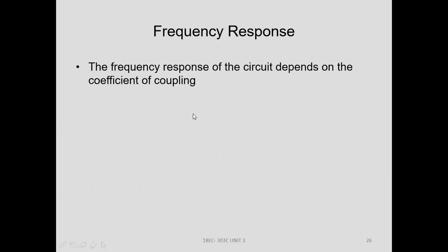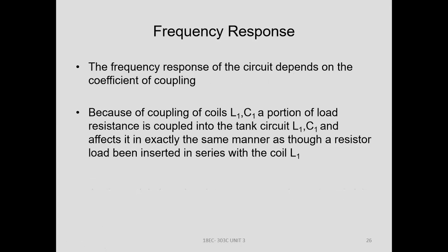The frequency response of the circuit depends on the coefficient of coupling. Because of the coupling of the coils L1 C1, a portion of the load resistance is coupled into the tank circuit L1 C1 and affects it in exactly the same manner as a resistor load being inserted in series with the coil L1.